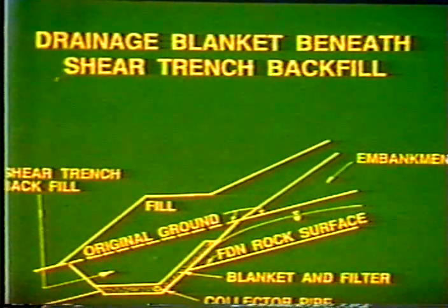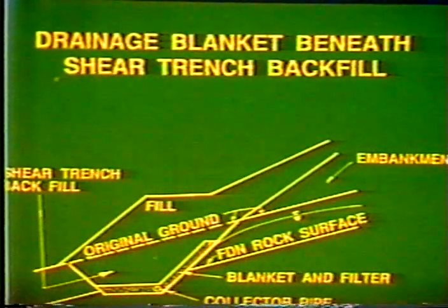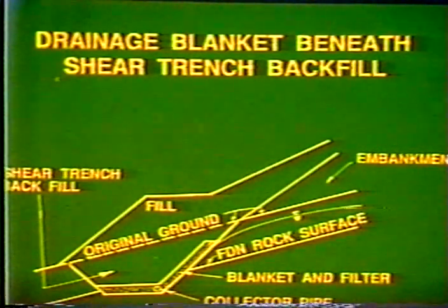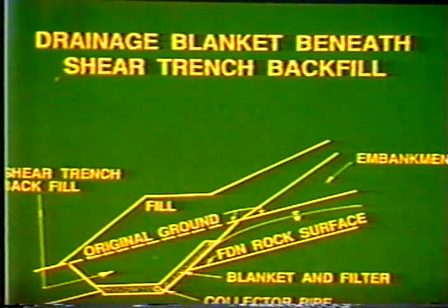Another scenario, we talked about slope flattening and berms, putting drainage blankets, and also I might mention in all these techniques, it's good to use a collector pipe. And then of course you need to slope the collector pipe or system to where it's draining, where you can get gravity drainage.